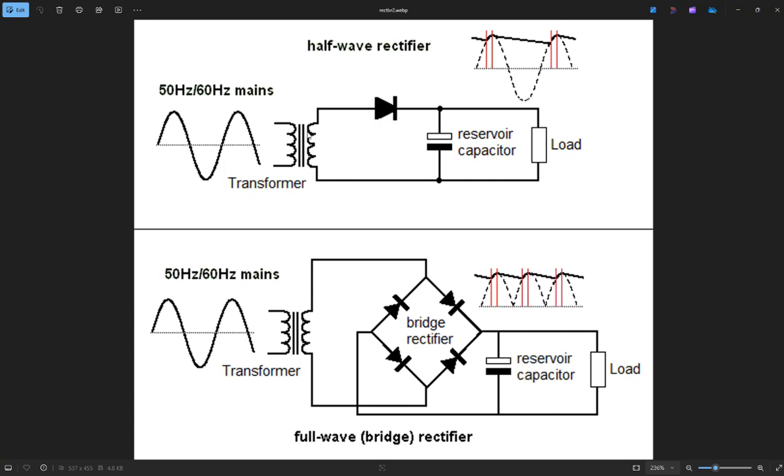So this is not something new. It happens in your everyday life, and everyone should know this kind of circuit. So you should know AC voltage comes in, first transformer, okay. Second rectifier, doesn't matter half wave, half bridge, or full wave, or full bridge, doesn't matter. You need a rectifier. So after the rectifier, it's going to be low pass filters to remove the ripples as much as possible. Get a very steady state or stable DC voltage.